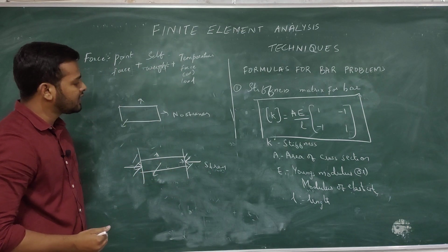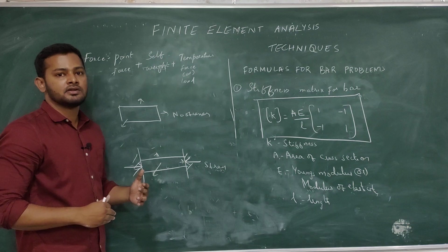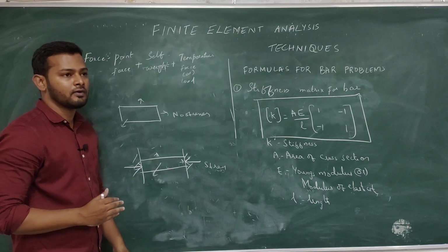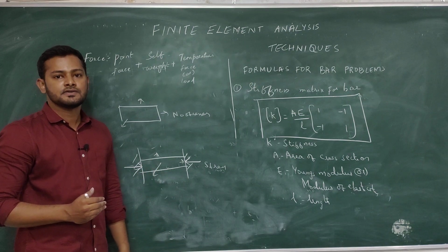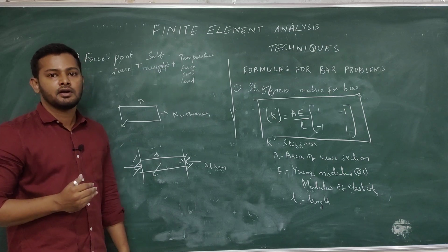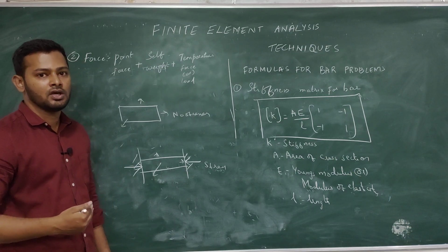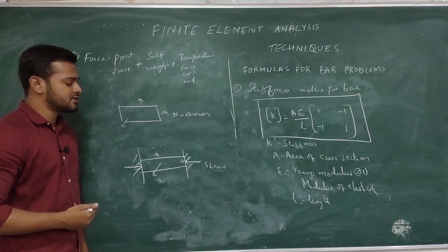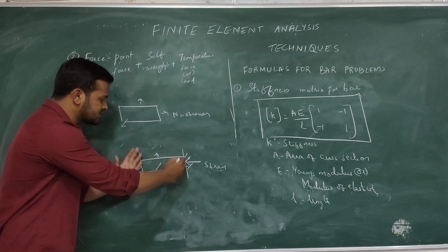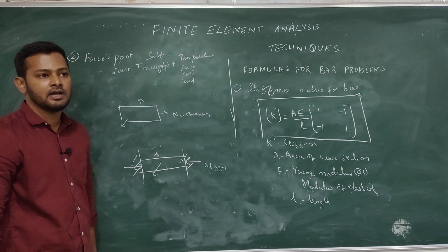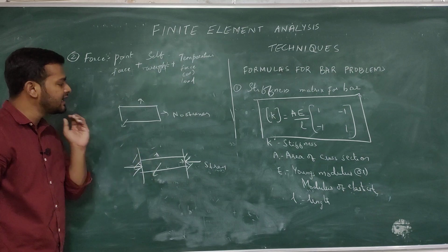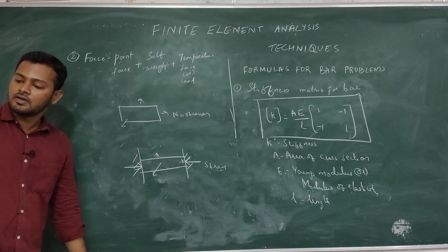Whenever you want to do something and someone is preventing you from doing that thing, what will happen in that case? Stresses will develop in your mind. So think in that way so that it would be easier for you to understand. So the supports are stopping this member from expanding. So in this case you have stresses developed.